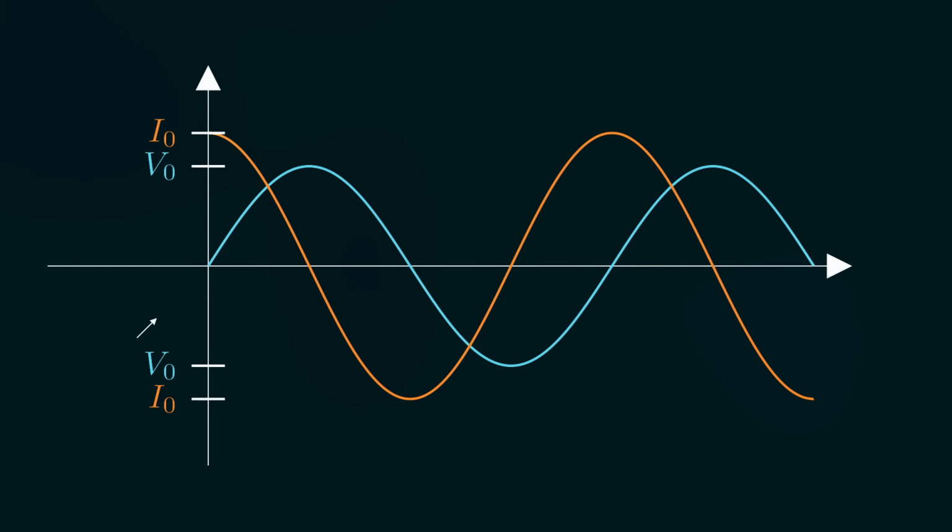When we first turn on the voltage, the capacitor acts like a wire, so it very quickly starts running current and accumulating charge. Then, the voltage starts to level off, and the current starts to level off too. The maximum charge stored on the capacitor occurs right here when you have maximum voltage, and you can see this since the charge is the area under the current curve. So right before the current goes negative, it's going to have the maximum charge.